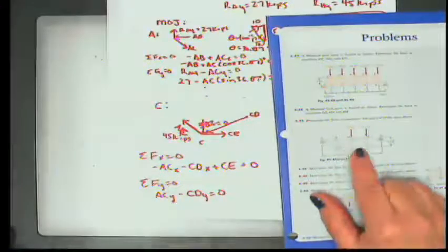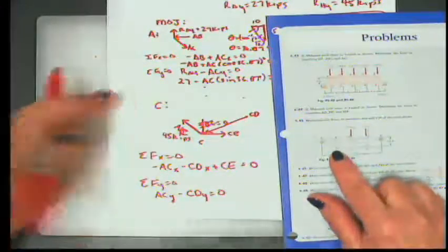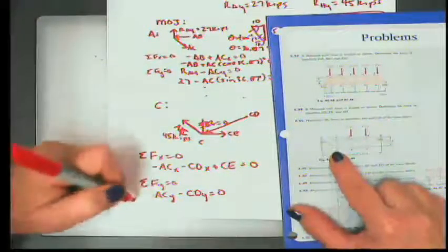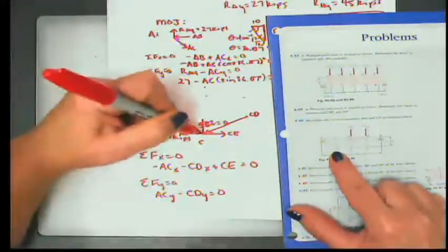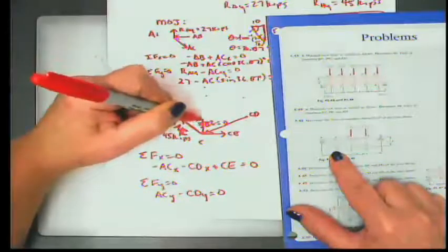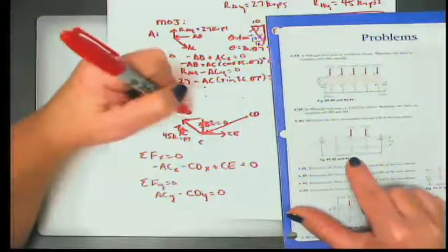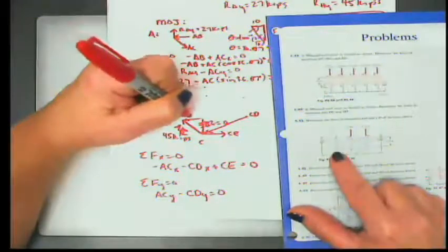All right, now we need to go back and do a little bit of trig, because the component of those 2 things in the Y direction are going to depend upon the dimensions of this truss. So AC, if we draw this little triangle right here, A to C, the distance from here to here, the horizontal distance, is 10 feet.